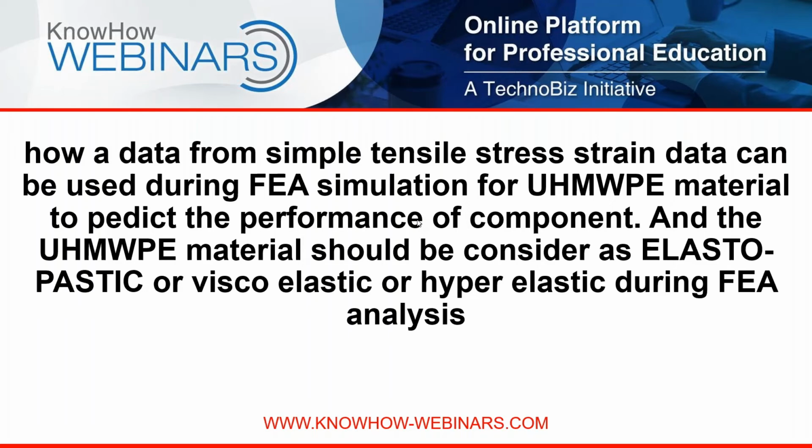But at the outset, it will be your judgment call. It will be the engineer's judgment call of how the material has to be modeled. And that judgment call will come from his understanding of what the outputs are and what he wants to simulate. A simple tensile stress strain data is not going to give you all the sophistication of a complex material model, which a viscoelastic material is, and which a hyperelastic material is, and which an elastoplastic material is.